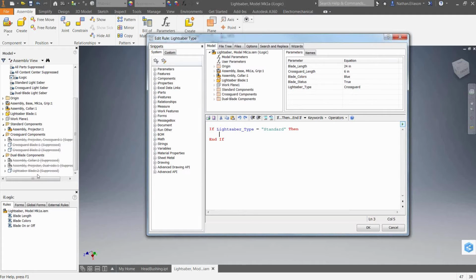then there's certain components that we want to suppress and unsuppress, like I reviewed with you earlier when we brought up the model. In this case, we want the assembly projector part unsuppressed, and we want all of these other 7 parts suppressed. Now I could go in here and double click this as active, and it would bring it up here, and then I could pick that specific part and say equals true or false to suppress or unsuppress it.